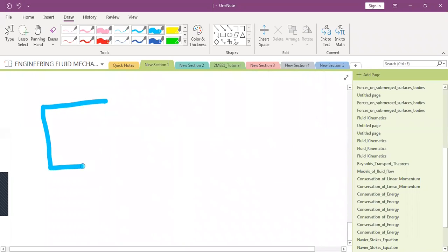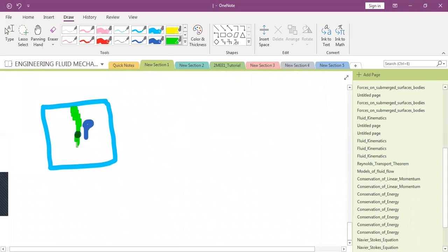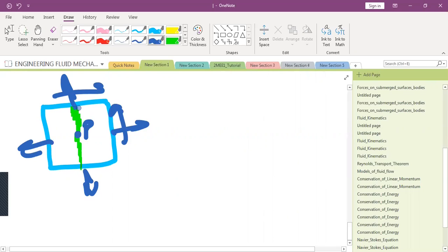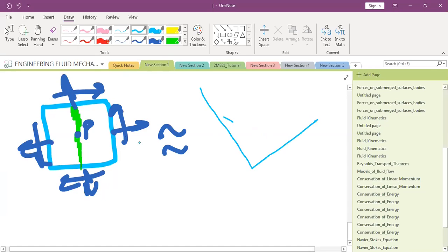If this was the object originally, you want to find out the stress at point P on a plane that is vertical. So you know that the stresses are shown like this on this plane. So you can actually convert this into a rotated coordinate system like this. So you can actually write down like this now.